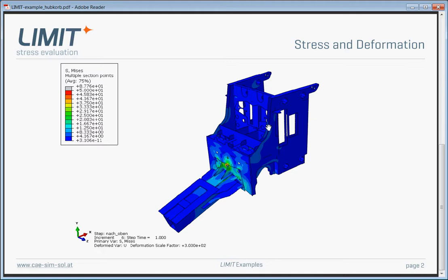The structure moves up and down, and these vertical accelerations, in addition to the gravity load, cause bending moments acting on this cantilever part, and furthermore causing local bending stresses here at the flange, between this flange plate and this larger flange plate welded to the larger part of the structure.